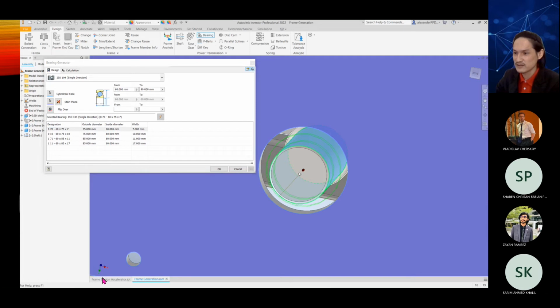Like just now, we already know that the size of this hole is 90 mm. But here you can see that they don't have 90 mm, for example, in ISO. So then you may need to choose one that is very close. For example, now I choose this one, 85.